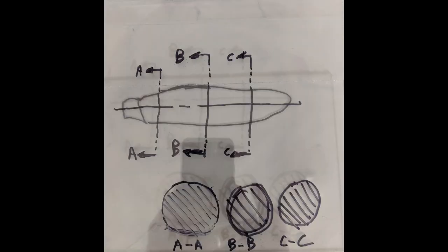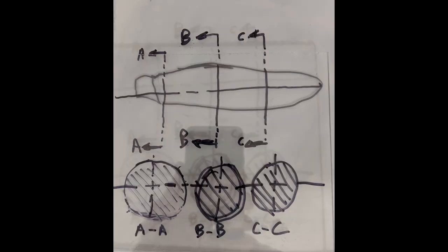In this next example, we have 3 sections through the top view, resulting in 3 removed views. If we take those same 3 removed views and align their center lines with the cross sections that they correspond to, it then becomes what's called an aligned removed view. That wraps up revolved views, and we'll move on to the next advanced section type.